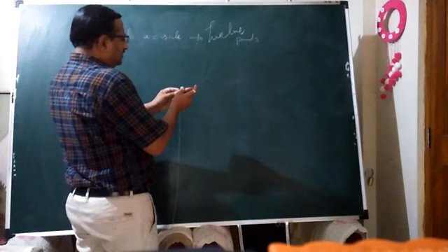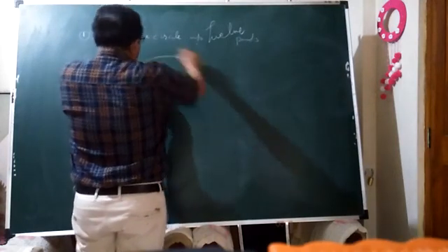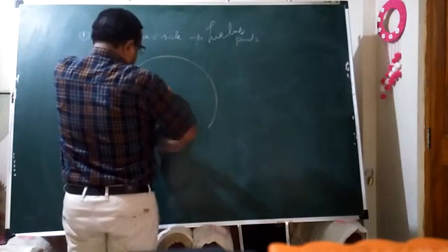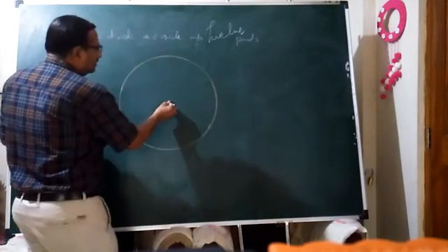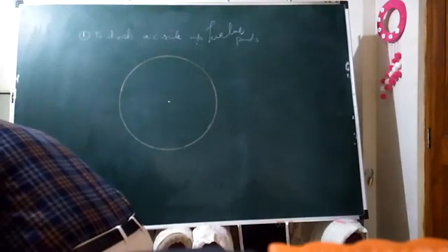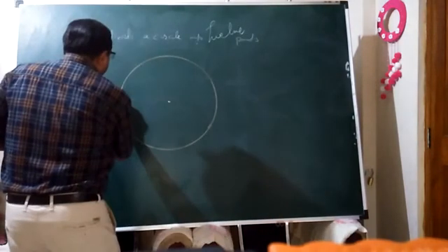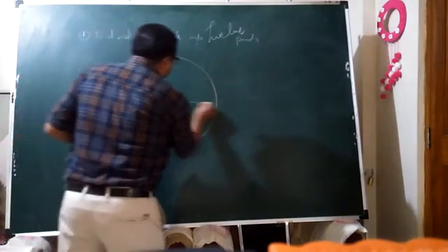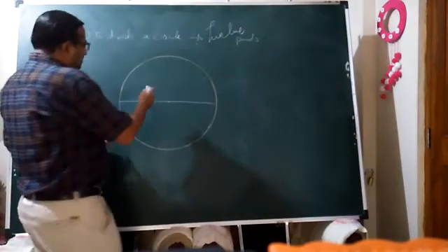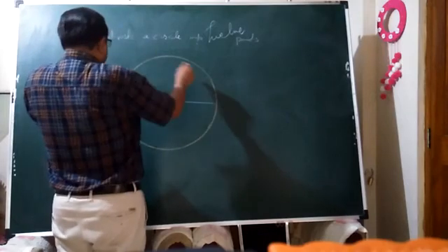Same way, either an 80 or 100 mm diameter circle, initially we have to construct in this way. Just like the earlier construction of 8 parts, first of all get the horizontal diameter line by the same procedure of picking more than half of the distance. Get the vertical diameter line also.